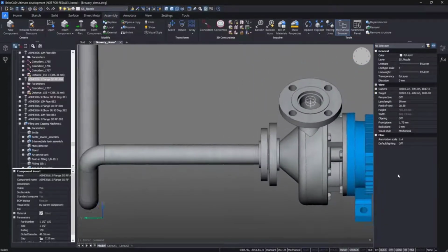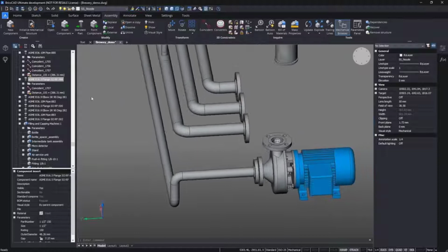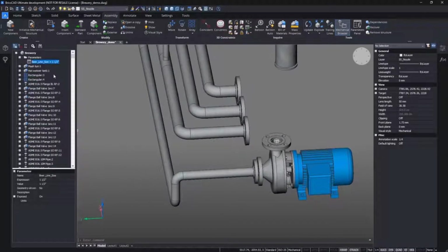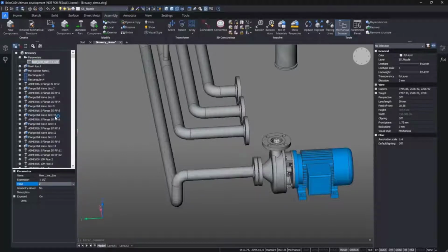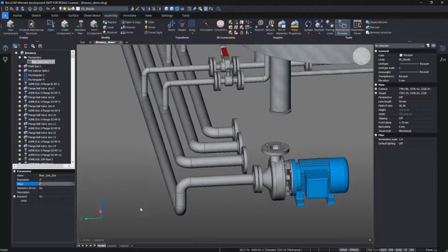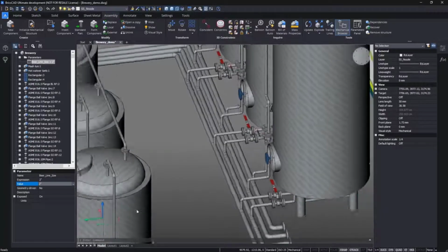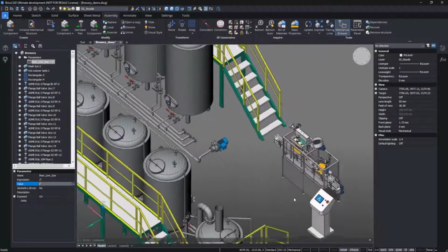As you can see, the outer diameter of the existing layout does not correspond to the pump diameter, but again, we have a properly parameterized layout, so we can adapt the diameter by changing only one parameter. So the flange, adjacent pipe, and all other connected pipes and tees will change their diameters properly.